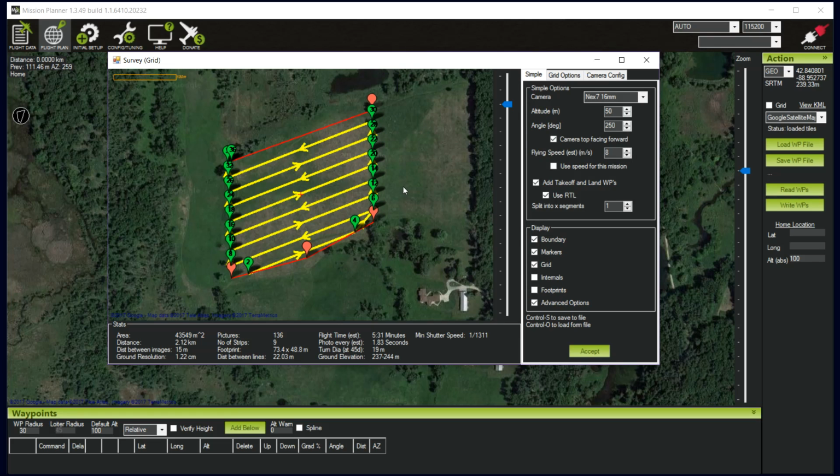All right, and in the field, we're going to orient these flight lines at 90 degrees or perpendicular to the wind. So this would work as long as the wind was coming either out of the northwest, or southeast, and that way the speed of the drone along each flight line will be fairly consistent. We'll also orient our grid so that we'll start in a corner that's away from us and fly closer to where we're taking off and landing.